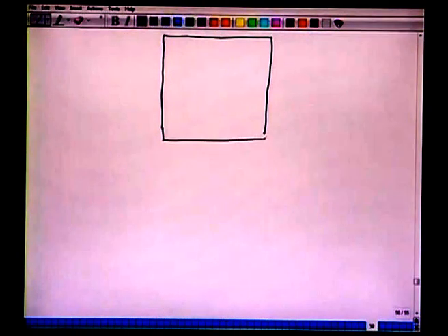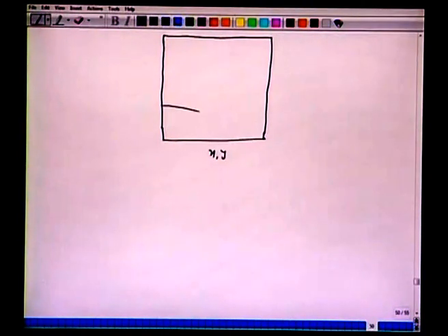Let's do it again here. So we have this HXY diagram for the complete distillation column. Let's do it one more time, maybe in a slightly different way. So we have XY, we have HL, we have HV here. Suppose we know this del D point, and how do we know? Of course, we can take the reflux ratio.